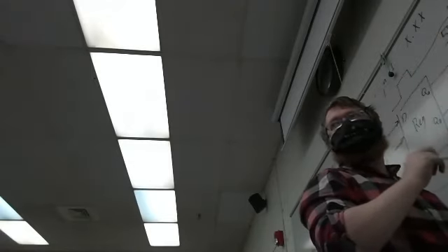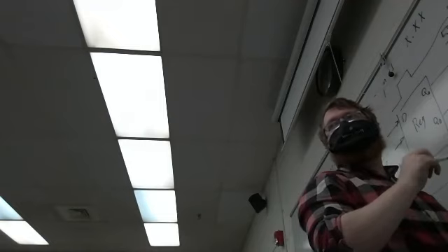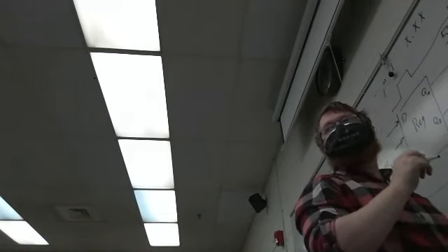So I feel like with the 200, 100 nanoseconds, isn't that pretty much the answer right there? Like, isn't that the only thing that is the same? Well, the big numbers are a good thing to start looking at. So what that means is the ALU has to be ready 200 nanoseconds before this rising edge of the clock. So the clock period would be 400 nanoseconds. That's the fastest you can have it done.